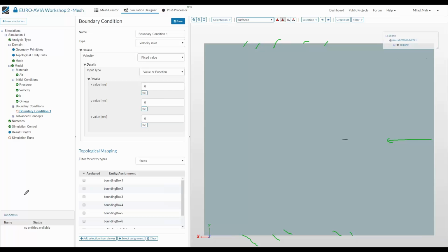But since we have this angle of attack, if you think about it like this, theoretically here air has to leave and here we need air to enter with the angle. Therefore, instead of putting an inlet here and an outlet there, we use this dedicated kind of boundary condition, which I will show you. But don't worry if it's confusing you. We also described the boundary condition in the tutorial, so let's call it inlet outlet, because it's both inlet and outlet.